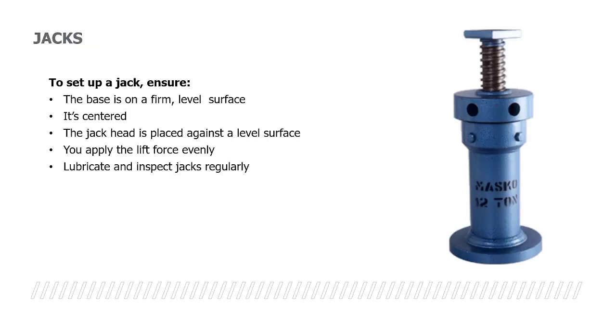And then we go right into another type of tool that you may find in the workplace, what they call jacks. One thing to keep in mind with any jack, no matter what type it is: make sure you're on a good base, a firm level surface. Make sure it's centered directly under the object you want to lift. The jack head is placed against a level surface. You apply the lift force evenly, and lubricate and inspect jacks regularly.